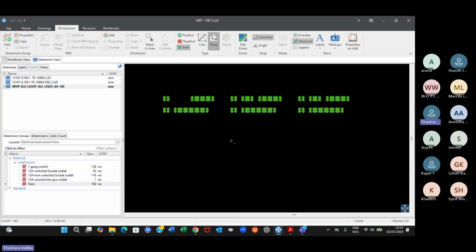And that will cover probably 50% of the quantification as far as MEP electrical is concerned, and you can apply it to bathroom fittings, electrical, ELV, sometimes manholes. If you have the same symbol, you can use it. But we know manholes will be slightly different because the invert level will be different, even though the same symbol is there.